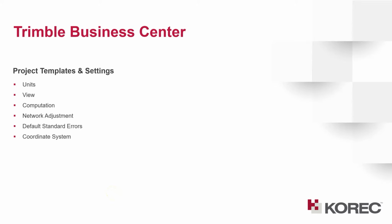So the first video in the series, this video, is going to deal with the project templates and settings, specifically looking at default settings for units, view settings, computation settings, network adjustment, default standard errors, and coordinate systems. In this initial series of videos, we're not looking in detail specifically at traverse adjustment or network adjustment, but as we're in the business of looking at the templates and the settings for those workflows, it makes sense to cover some sensible defaults whilst we're setting up the templates.